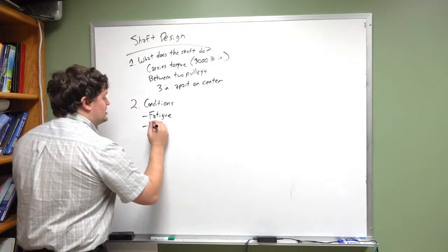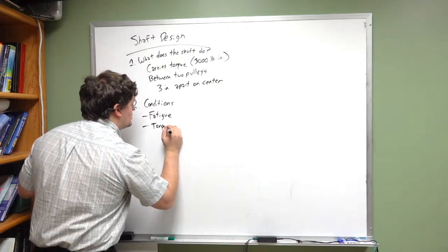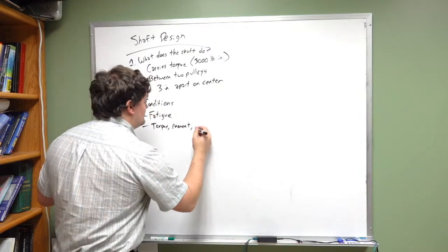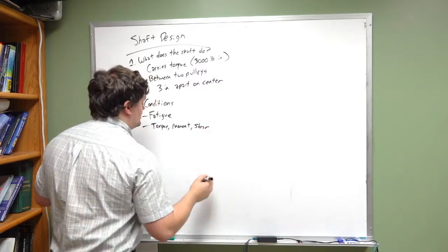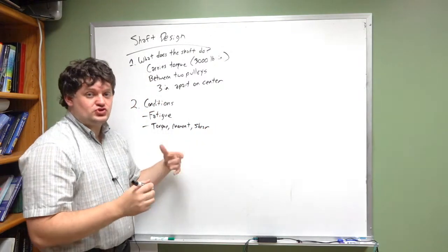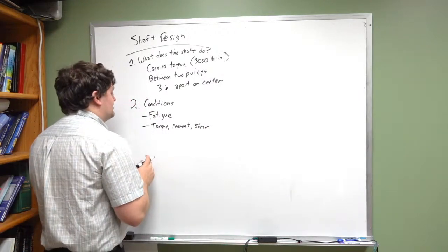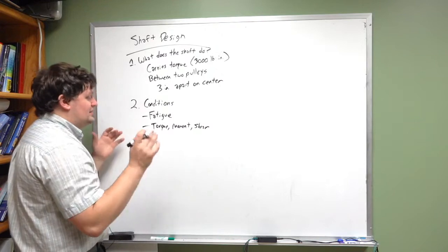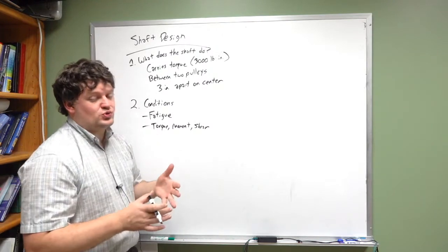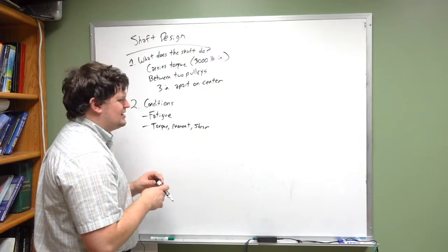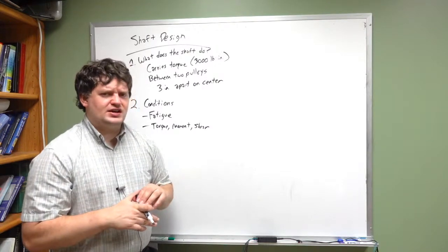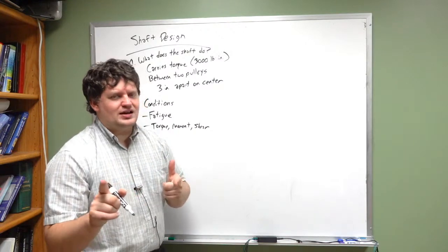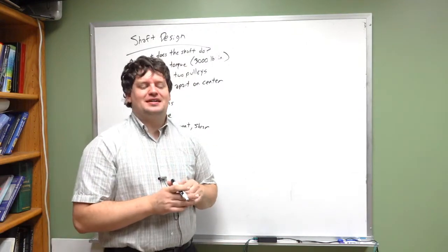Beyond this, we know it's not just going to be carrying torque, but it's also going to have a moment load, and it's going to have a shear load. So we'll have three different stresses present for this, and we have to consider it in fatigue. And really, we don't have any other conditions for what the shaft has to be. Now, what the book suggests for shaft design,